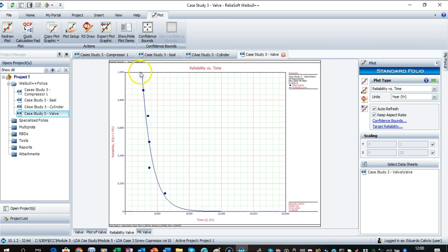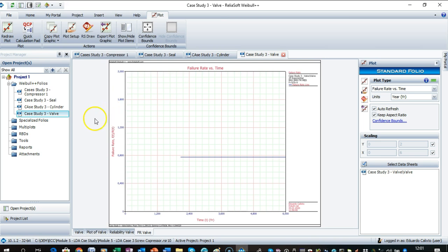So what we can do in this valve is, at exactly this time here, before failures happen, establish an inspection and test of the valve, because it's random. We don't know the real time, but we can see based on the reliability. After this time, the reliability starts to decrease very fast. So we can establish this time based on reliability, or even some reliability targets that we expect after this time. As reliability goes down, failure starts to happen. As we want to be preventive, we can define such an approach to detect failure.